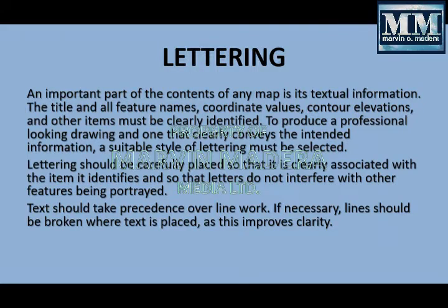Lettering should be carefully placed so that it is clearly associated with the item it identifies and so the letters do not interfere with other features being portrayed. Text should take precedence over line work if necessary. Lines should be broken when text is placed, as this improves clarity.